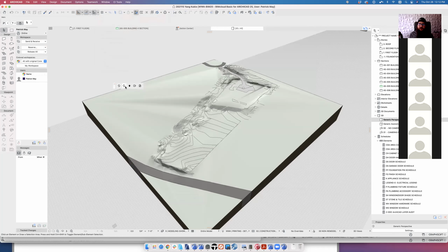There is a live plugin option. So if you have an Archicad file open and a Twinmotion file open at the same time, you can import into Twinmotion that Datasmith link. We need to run some more tests before we know whether that works or not. But the traditional workflow of just export, import is still going to apply.